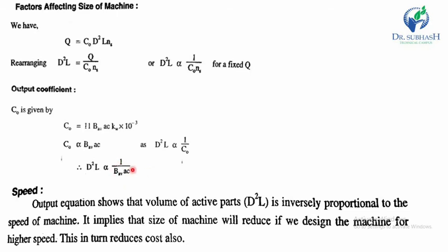From an economic point of view, we should use values as high as possible. However, a design engineer must also see the effect of increased loading on performance characteristics such as power factor, temperature rise, losses and efficiency. And we should choose a value of specific loading which gives an economic design and satisfies the requirement specifications with good reliability.